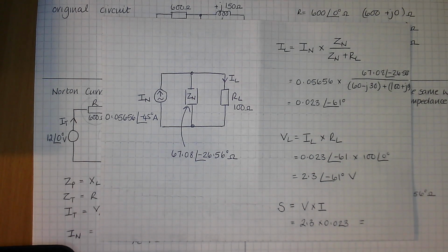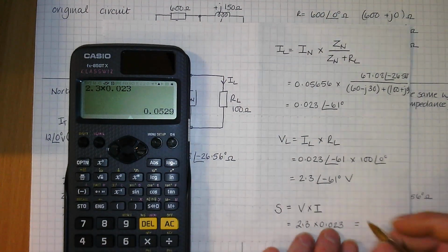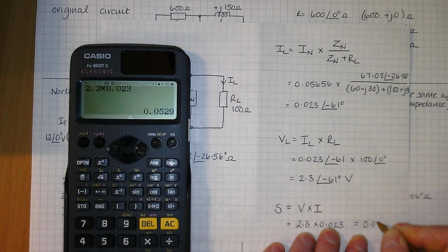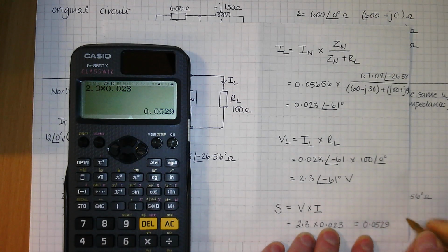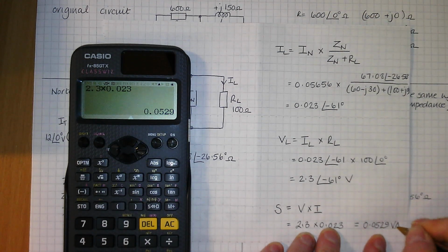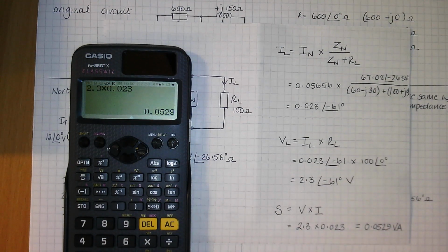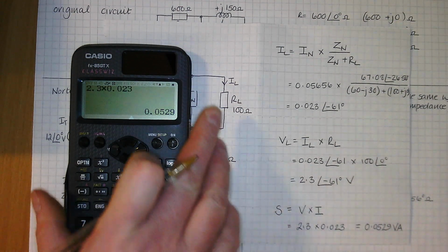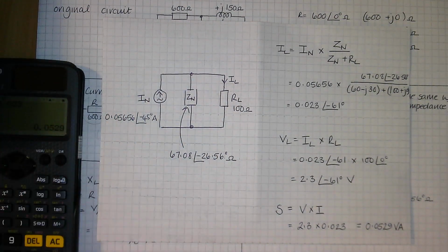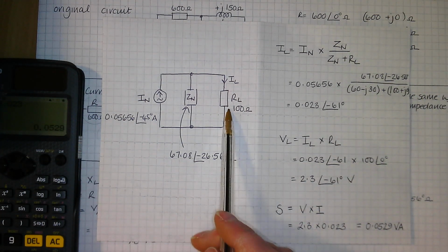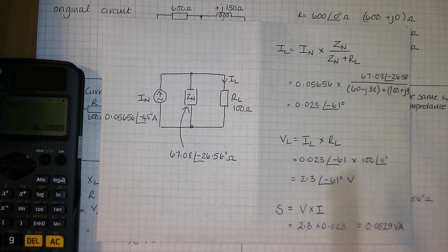I think that came up in one of the questions last week. And it's apparent power. Not measured in watts, it's measured in VA. Although in this occasion, because it's a resistive load, there would be no Q. There's no reactive power. So your P would be the same value as that.